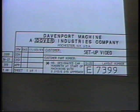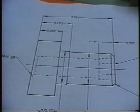Specific layouts are identified numerically in the title block, which is located in the lower right-hand corner. Tools supplied by Davenport for each specific job will be marked with this number followed by a dash number. Directly above the title block are the dimensions of the piece part that is being produced. This drawing contains the tolerance limits required in the production process.